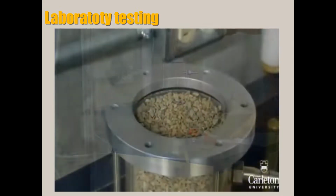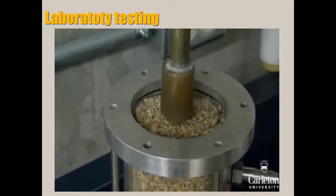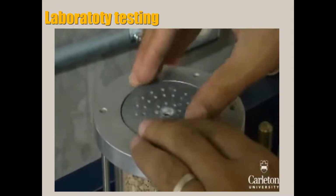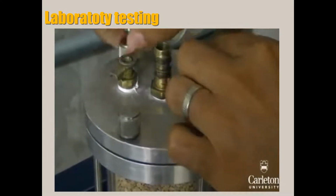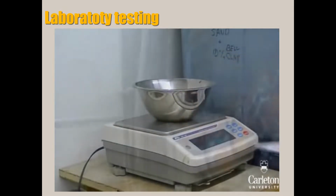The top surface of the soil in the cylinder should be level with a small space for the screen and end cap. Place the screen on top of the soil as well as the separator. Next, place the cap on top of the cylinder and secure it with 3 screws, like this. Record the mass of the container plus the remaining soil.